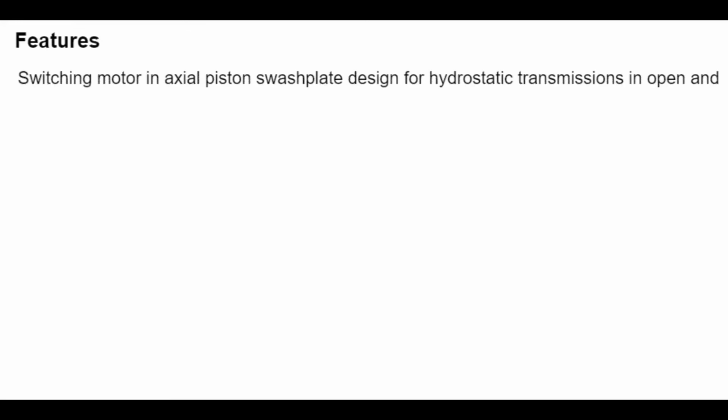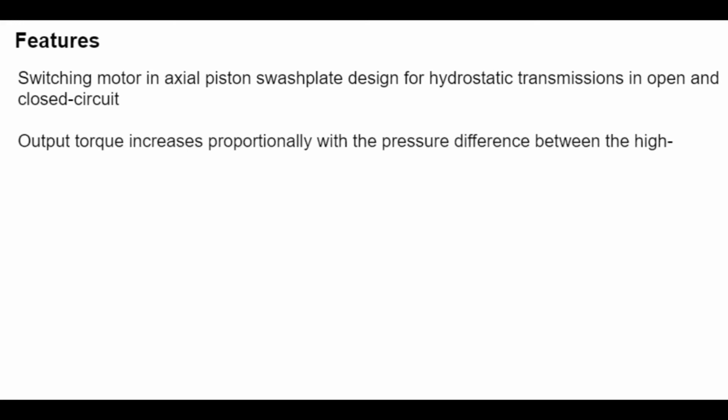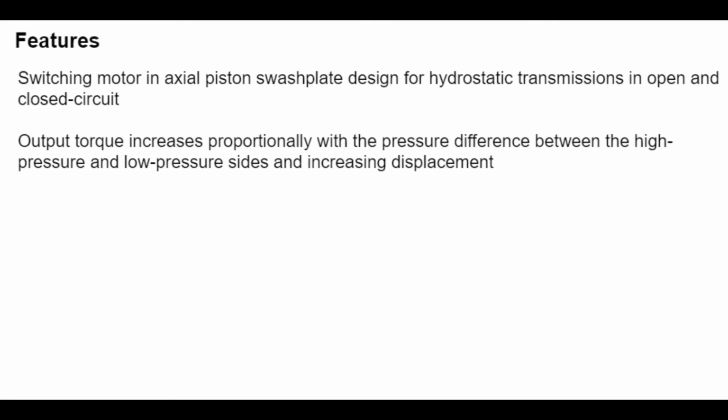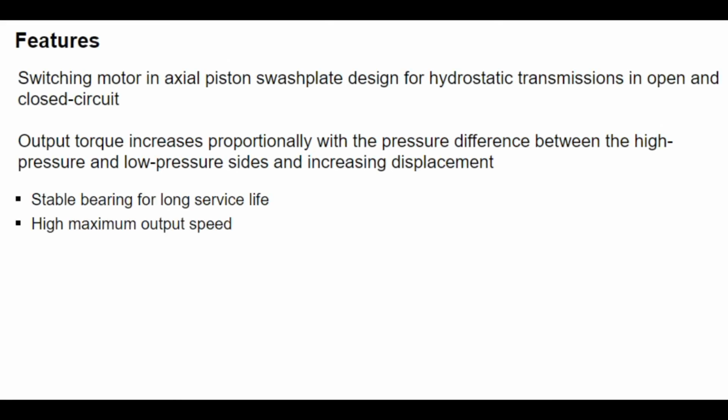The Rexroth axial piston switching motor A10VM in swash plate design is specially designed for medium-pressure hydrostatic drives in open circuit and closed circuit with minimal space. Output torque increases proportionally with the pressure difference between the high-pressure and low-pressure sides and increasing displacement. The stable bearing ensures long service life and very reliable output speed. Other features include a good power-to-weight ratio and low noise.